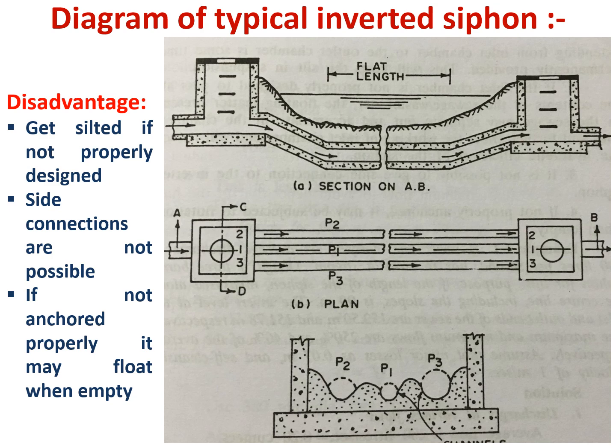Here you can see in this typical inverted siphon figure, 3 pipes are provided, P1, P2 and P3. Here is the first manhole, the second manhole, and this is your obstruction that you have to take this pipeline beneath. P1, P2 and P3 will work in different conditions: average, minimum and maximum flow condition.